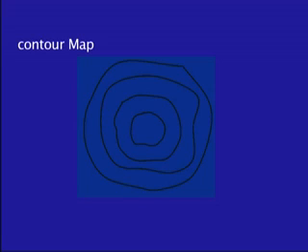That is, each curve or a contour is the result of joining all those points which have a given height or altitude. Another contour corresponds to a different altitude, and of course, these heights or altitudes are shown alongside these curves. For example, this may be a height of 100 meters, this may be a height of 105 meters, and so on.